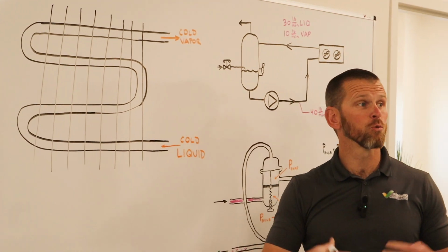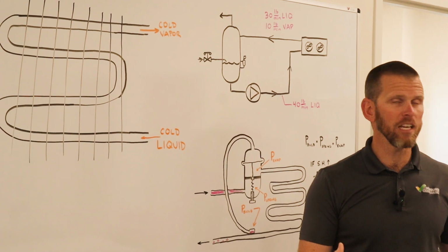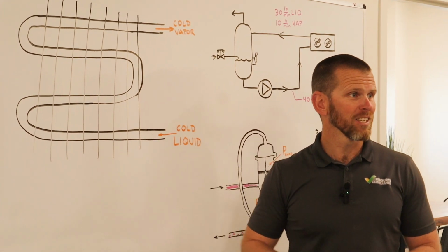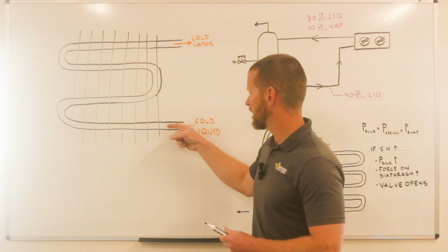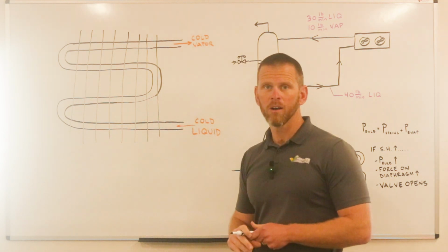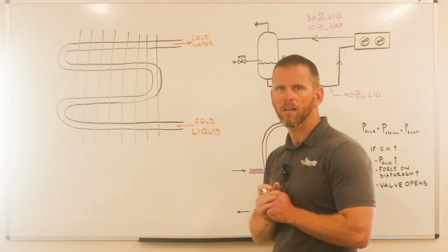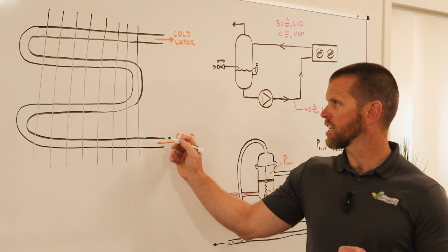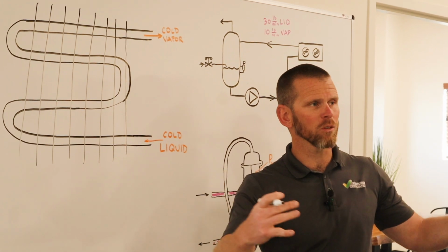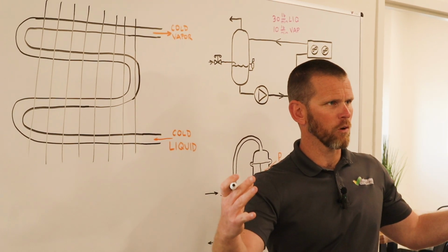That this would drastically increase the rate of heat transfer. And that's because we've just increased the surface area. So instead of the air only contacting the tubes, now it's contacting the tubes and the fins. The fins are made of thin aluminum or some conductive metal. Therefore, as they touch the tubes, the temperature gets uniform across those fins. So now we have this great heat transfer area.